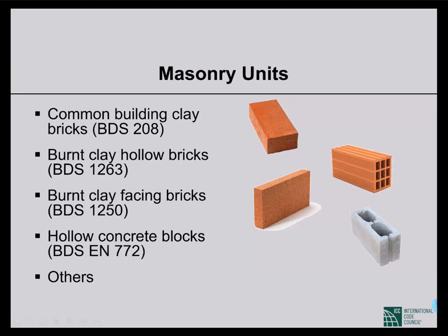Then there could be hollow bricks. In Bangladesh, these are mostly ceramic clay hollow bricks. We have a separate standard for this type of unit, that is BDS 1263. We can use facing bricks, which are also made of burnt clay.